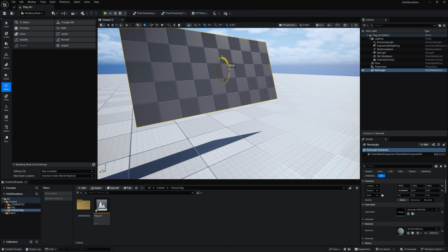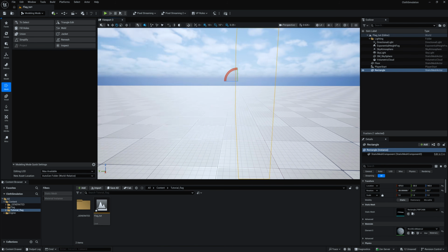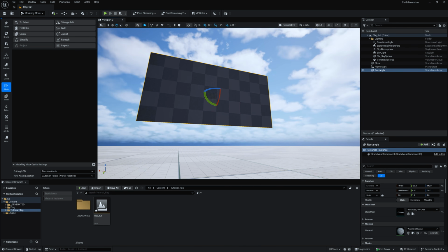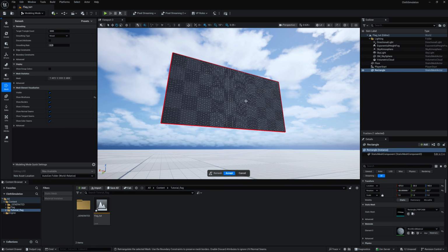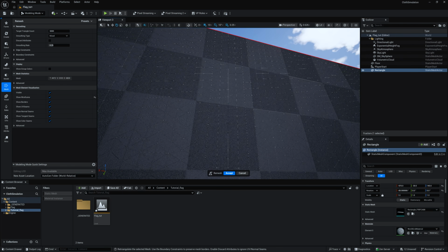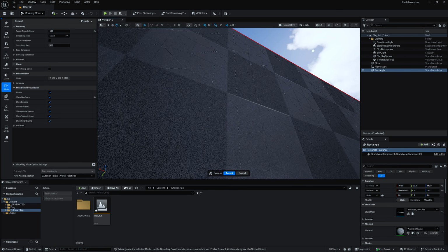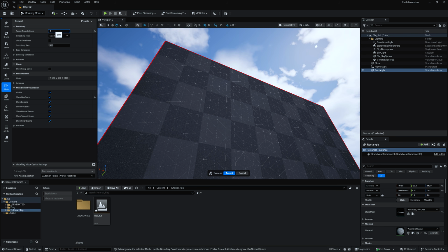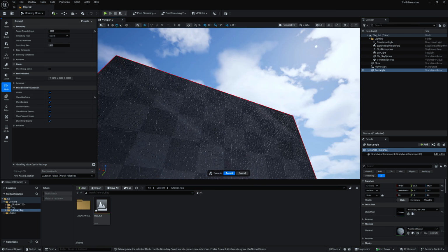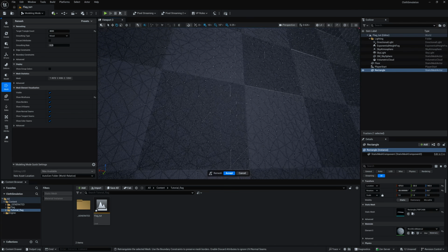Now rotate this something like 90 degrees so that you can see what exactly is going on here. Now you need to click this remesh option. Once you click this remesh option, you can find out a lot more polygons are here. If you want a smooth kind of simulation, you can increase this, but if you just want it for checking purposes, you can reduce it to like 600 or 500. As you can see, the polygons are reduced, but as of now I am going to use 8000. Make sure you save the project file once you increase the polygon count.